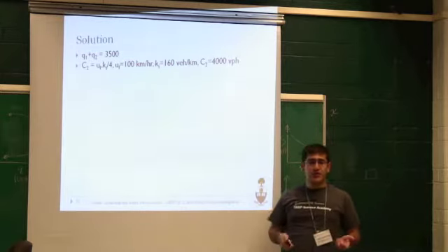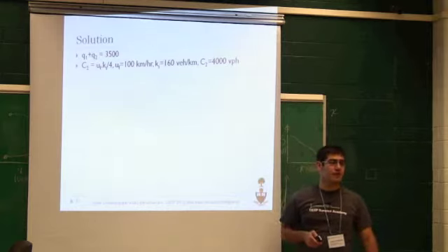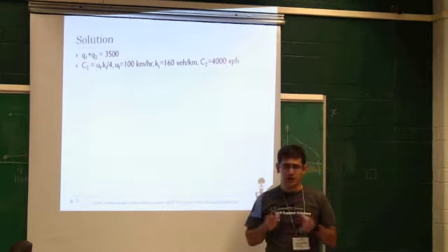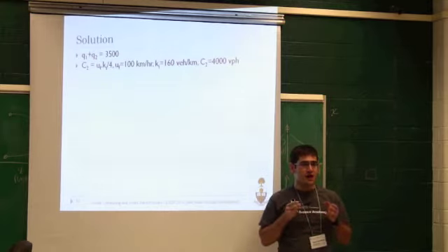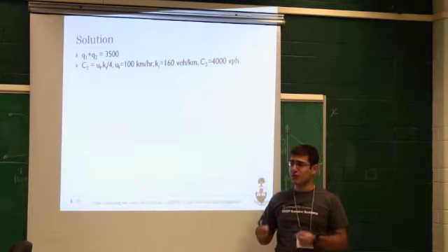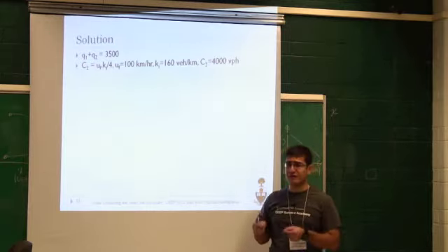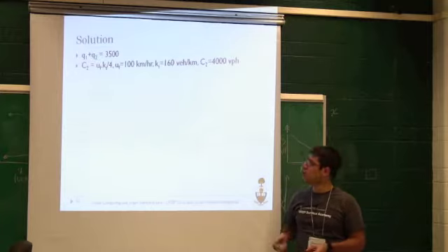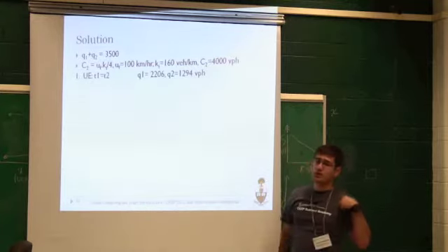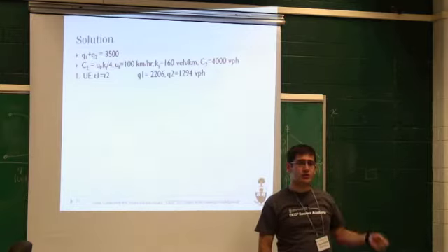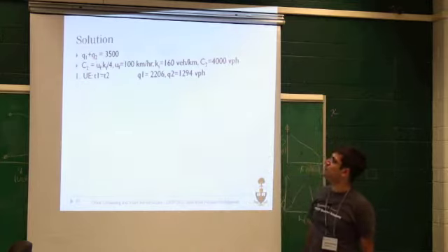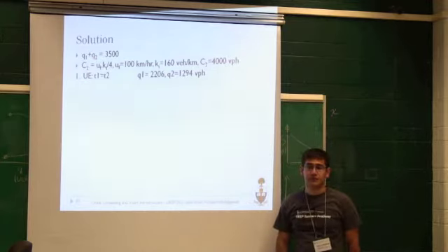After this, I come up with the other formula, which is by definition for user equilibrium. Vehicles will reach equilibrium when they have no incentive to change their routes. That is because the travel time of one vehicle on link 1 is equivalent to the travel time of one vehicle on link 2, which means T1 equal T2. Okay? So you have T1 equal T2. You end up with two equations, two unknowns. Those equations would be with Q1 and Q2, and you solve them, and then you get these values.